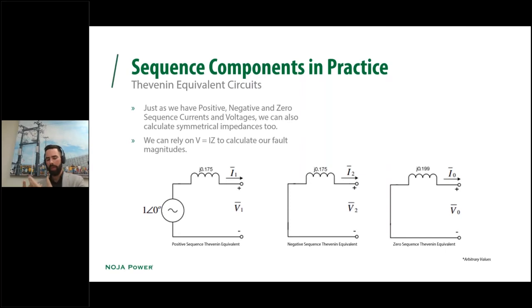Now, if you apply that to a machine whose impedance has an inductive component, relative to the spinning direction of the machine, you're actually going in the opposite direction at the same time. So negative sequence can appear as 100 hertz, which is twice the frequency of what the scenario is. What that basically means is that your negative sequence impedance, because it's an inductance, the higher the frequency, the higher the impedance, so you're going to get a slight increase on the negative phase sequence impedance as well.